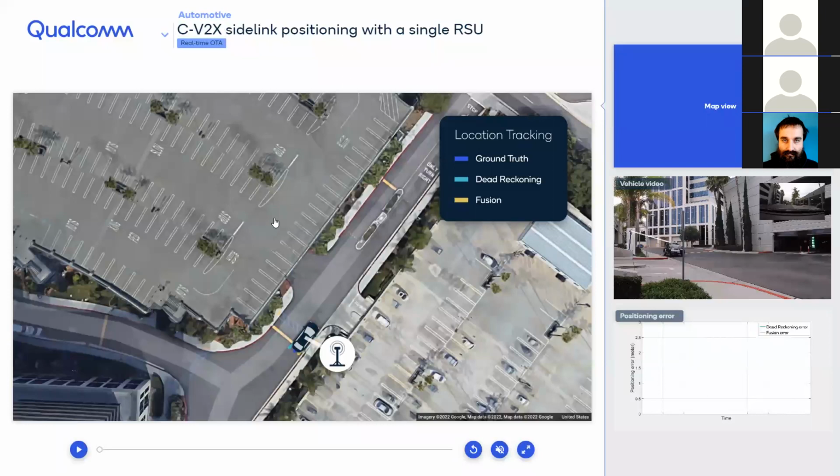Okay, so I've explained before that this is the case where we use an RSU to replace the GNSS signal completely, because in this case, the GNSS signal is completely lost. If you think about it, when you have GNSS, it means you have connection to the GNSS satellites, and not just a single connection. You have to be able to detect at least 3 or more satellites. 3 is the minimum, but normally you need more to have a good fix of the GPS or GNSS signal.